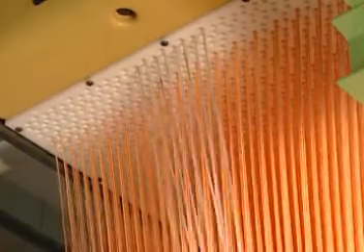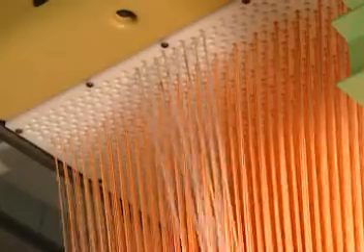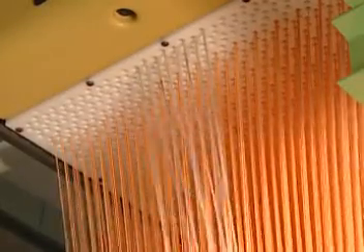Fabrics made on Jacquard looms are normally more expensive because of their complexity and slower weaving speed. There are no harness frames on this style of loom. Each end is activated independently, being controlled by its own harness cord from the Jacquard head. The harness cord is attached to a heddle, which is pulled down by a spring in most cases, but in some of the older and slower models, weights are used to pull the heddles down to achieve the pattern.